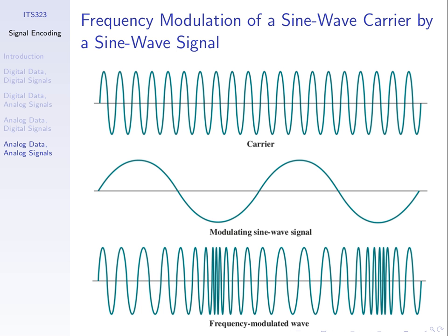And in all of these cases, we can transmit our data no matter what the spectrum of the input data is, voice of just 0 to 4,000 hertz, we can transmit it at any frequency in our spectrum. FM radio, the voice, is transmitted at, say, 100 megahertz approximately. When my voice is input into the microphone and goes to the wireless transmitter, this transmitter from memory transmits, I don't think it says here, actually I can't remember, I did it last year, some wireless transmission of, I think it was, 700 or 800 megahertz is the frequency of the wireless transmission from this transmitter to the receiver on the desk.